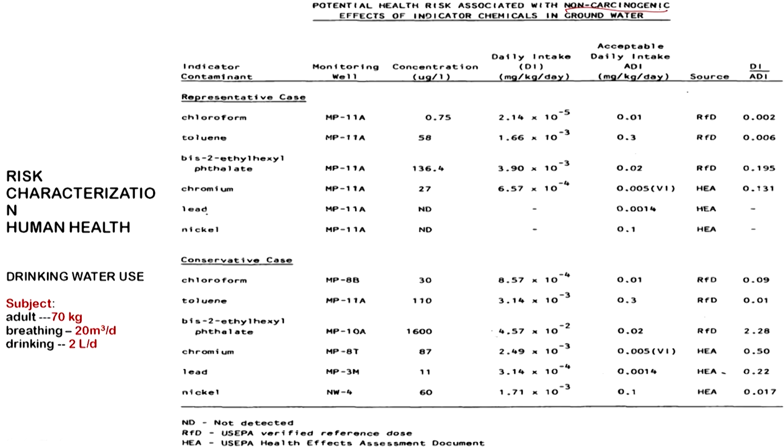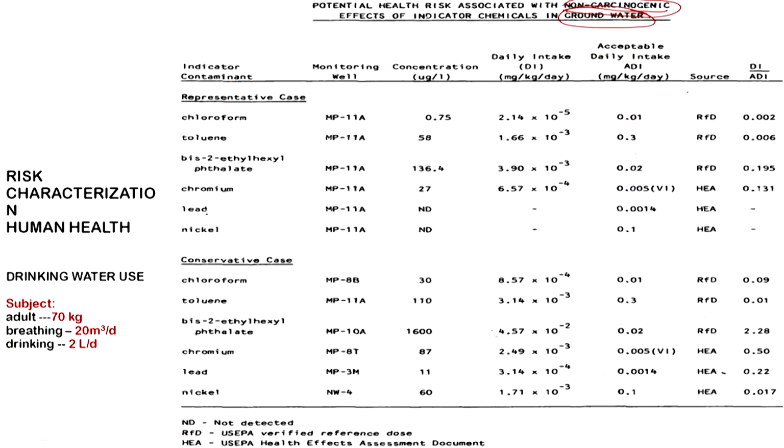Here I am now going to look at non-carcinogens. Earlier we looked at carcinogens. We are now considering the case where groundwater is again contaminated, and I am ingesting that groundwater, and I am looking at non-carcinogens. Again, concentration, daily intake, and acceptable daily intake or reference dose, and then I am going to calculate the hazard index.